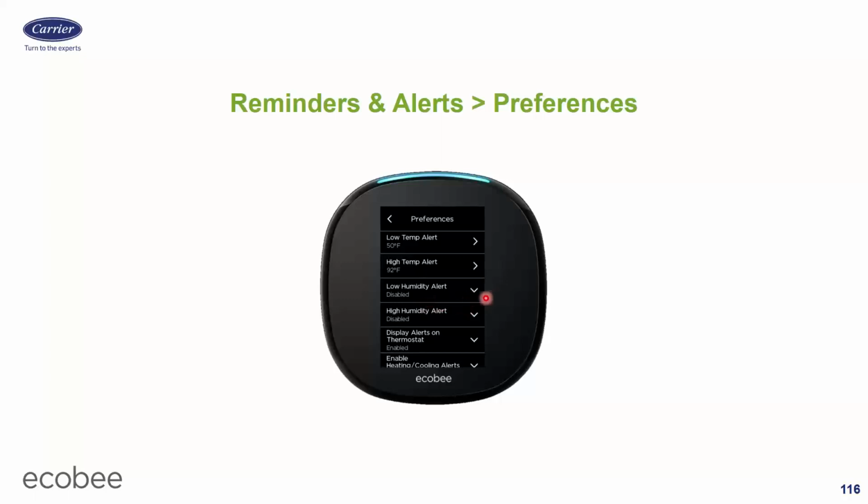Low humidity alert, I almost always set this for 10%. You can set it higher. The problem with that is most people are going to use the frost control, which means they're going to have a low humidity set point when it's a 0 or 10 degree day. So it's going to get down near 10%. It shouldn't get below 10% though. So I usually set it for 10%. If it goes below 10%, that probably means my humidifier is not working.